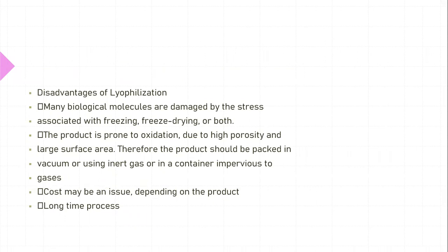What are the disadvantages of lyophilization? There are disadvantages as well. Many biological molecules are damaged by the stress associated with freezing, freeze drying, or both. There can be materials which do not require to be frozen. The product is prone to oxidation due to high porosity and large surface area. Therefore, the product should be packed in vacuum or using inert gas or in a container impervious to gases.